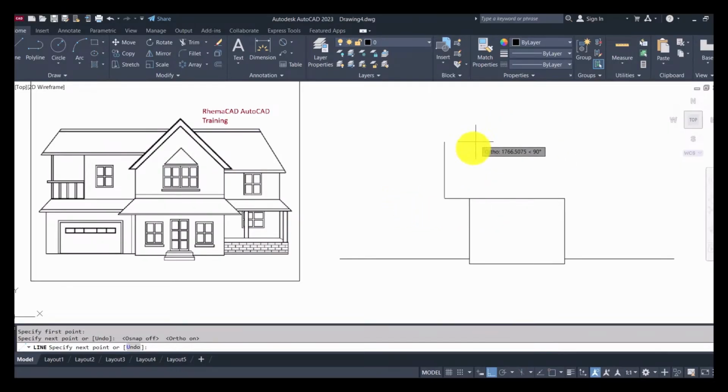All right. Now I want to draw an inclined line. I don't need auto again. So you can see how I've been navigating using auto and taking auto off. Okay, I draw this line. I need my object snap to pick this point once again. So I'll click on object snap, and don't forget, once you are done using it, put it off. Now I need my auto. Okay, so trim, enter.